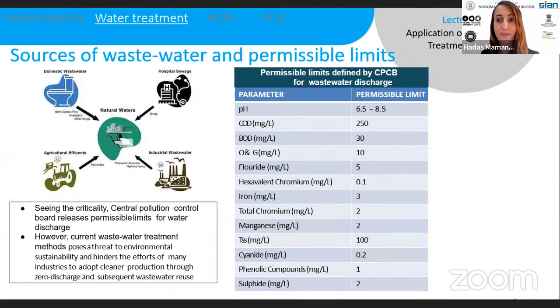For example, drugs like carbamazepine and sulfamethoxazole have concentrations in micrograms per liter or nanograms per liter, so their impact on the COD is very low. Therefore, we can meet the permissible COD limit but still have residual organic contaminants in our wastewater that we need to treat. Now, there are a few options to treat these types of residuals, which we will talk about